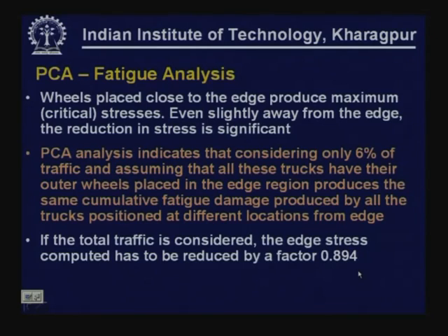For carrying out fatigue analysis, that means for calculating the wheel load stresses, the wheels placed close to the edge produce maximum stresses. Even if the loads are slightly placed away from the edge, the reduction in stress is significant. So, it is important to understand what percentage of wheel loads are going to be placed close to the pavement edge. All those loads that are placed even slightly away from the pavement edge, it is seen that the reduction in stress is significant and it is not going to be significantly contributing towards fatigue damage. So, we are concerned about those wheel loads which are placed very close to the pavement edge.